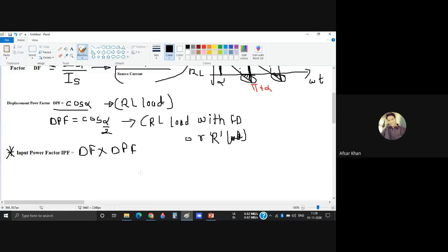Yes, sir. So these three formulas, and last is finally THD. That is very, very important. THD, total harmonic distortion. The total harmonic distortion formula is nothing but the square root of (1 over distortion factor) whole squared minus 1. This is your distortion factor. You have seen all these formulas in analyzing rectifiers and inverters in your power electronics.